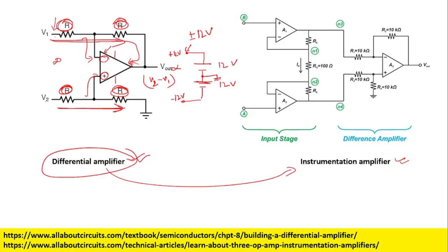What is our aim? Our aim is to measure the potential, biopotential. Potential is nothing but the difference in the voltage at 2 points. So basically, we are trying to measure the voltage, right? So what should be the input impedance? It should be high. But in the case of the differential amplifier, what is happening? We are having finite resistances. That means it is having very low input impedance. So when this happens, there is a phenomenon which is called loading.